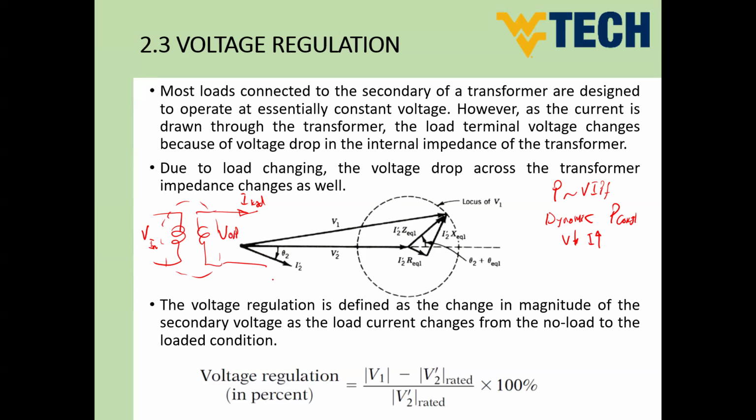We should find a solution for our loads or redesign our transformer in order to have lower voltage regulation, because by the end, volt regulation is going to be a function of the impedance of the transformer. So if we couldn't redesign our transformer, we have to provide a solution to keep the volt constant at the load side.